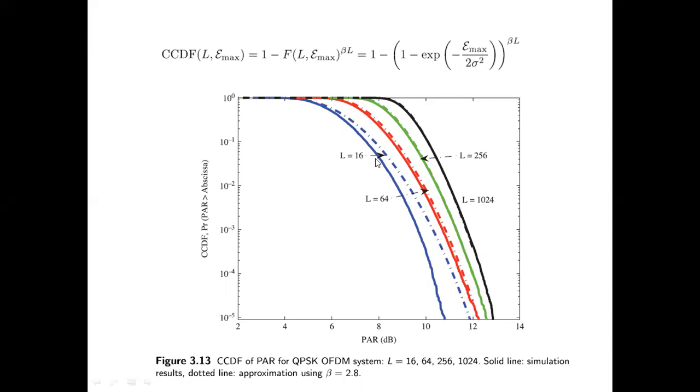As I said to you, if I have 8 ones and I take an FFT, my answer is suddenly going to be an 8 at 0, right? Imagine a 1024-point FFT of a sequence of all 1024 ones. Then I am going to have a very large value of 1024. It's a concern. The moment you take an FFT, you tackle fading very nicely, but the peak to average power ratio is a concern, and somehow it needs to be tackled. You can see a higher FFT size makes it much worse.